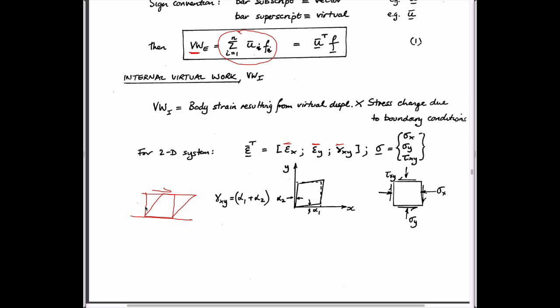Ends up shearing like this. This angle alpha is equal to the shear strain that occurs. So this shear strain is basically that. And so likewise, almost directly analogous to displacement times forces, strains times stresses. Strain is kind of a displacement that changes in space. A stress is a force that's applied over a certain area, so they're equivalent to each other.